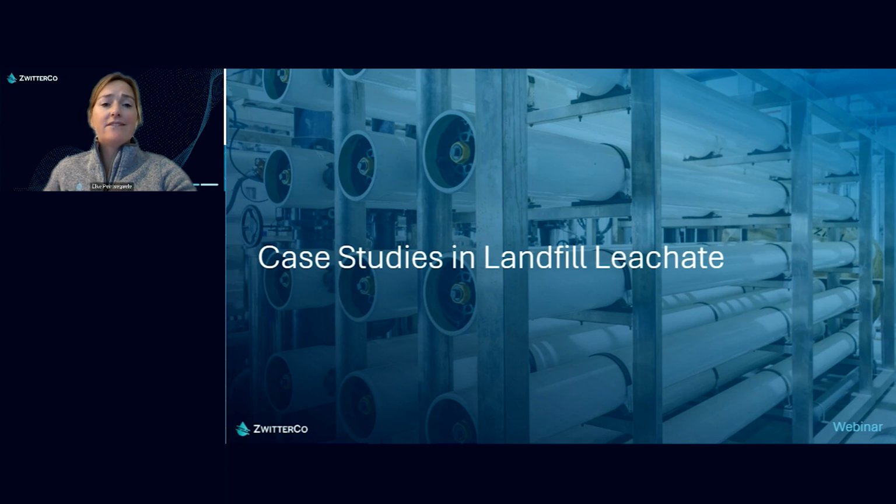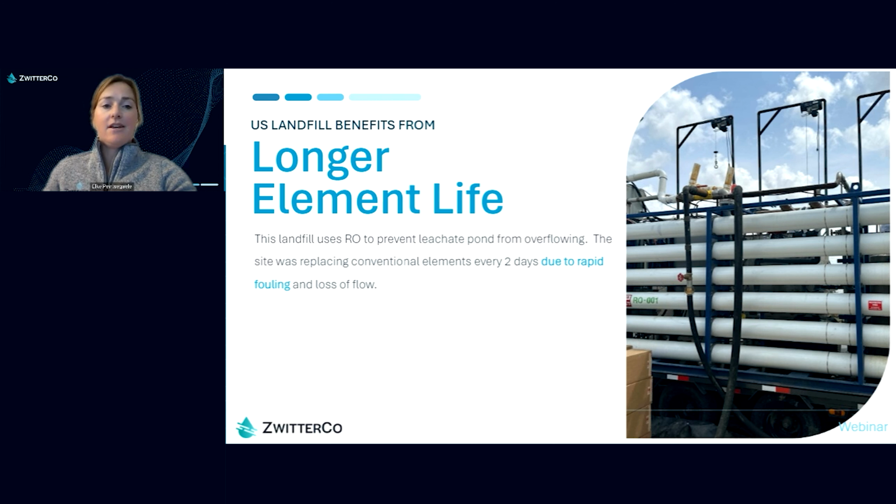So with that, let's look at some landfill leachate case studies using ZwitterCo RO membrane elements. So the first site is a landfill in the US. The site collects leachate in a pond on site and uses an RO system to treat that leachate so that the pond doesn't overflow, specifically during the rainy season.